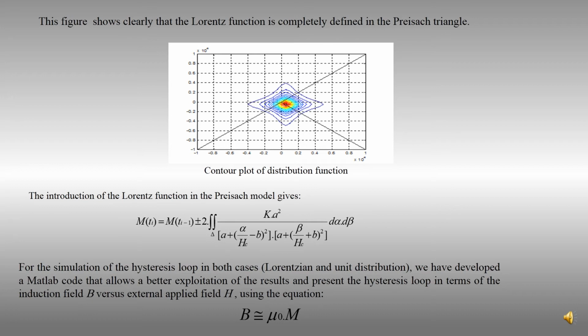For the simulation of the hysteresis loop in both cases, Lorentz and unit distribution, we have developed a MATLAB code that allows better exploitation of the results and presents the hysteresis loop in terms of the induction field versus the external applied field using the known expression shown here.